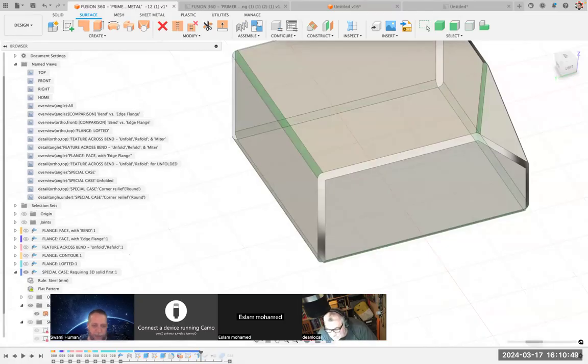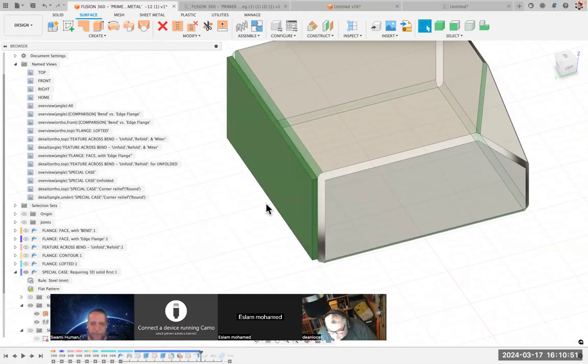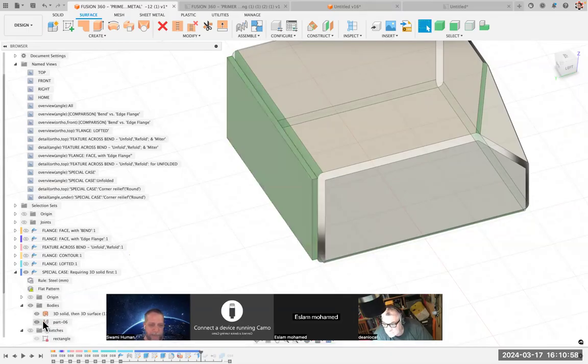I project in the geometry to get that face. So that one has now been created here in our tree. And you see the icon. That new green one is in fact a proper sheet metal object. Because we're going to turn this surface into a solid by thickening it, but then we need to join it, combine it with this other one finally to make it one final sheet metal body in the full shape we need. So let's go ahead and do that.